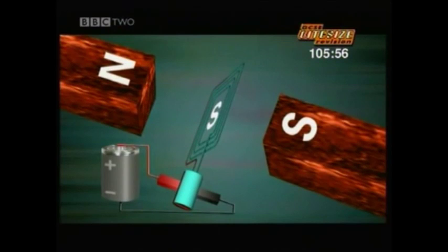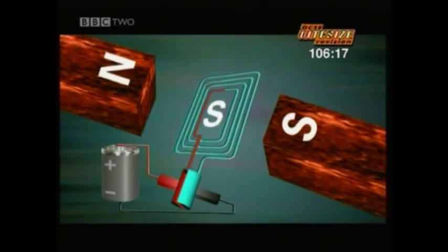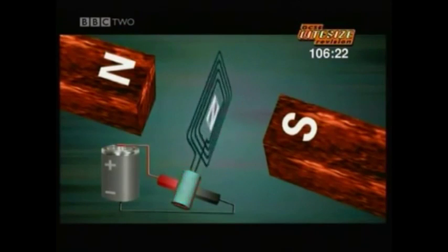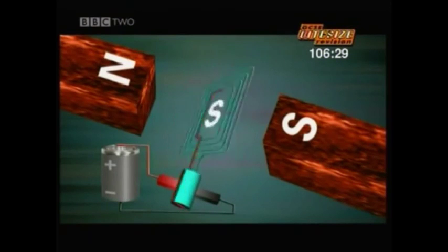But just at the right moment, the sliding contacts flip the direction of the current. So the magnetic field in the coil flips too. Now the coil's south pole is next to the south pole of the motor. Similar poles repel each other, so the coil is pushed away and it keeps on turning. Half a turn later, the contacts flip the current again. So the cycle repeats. The coil never quite gets to where it wants to be, and it will keep on spinning until the battery runs out.